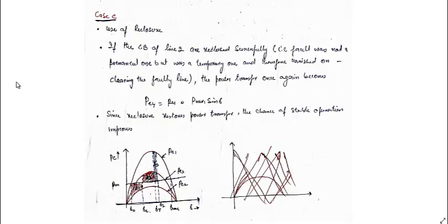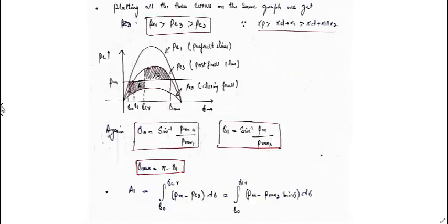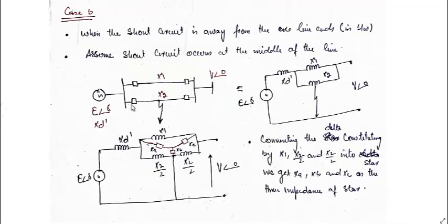You can see that when the reclosure happens, these two circuit breakers have been closed again. Which ones? These two circuit breakers. The fault is cleared first, so the line is removed when the fault occurs. This is the same thing done in case C also until now. But before doing any inspection and then restoring this line after one day, half a day, or any number of hours, these two circuit breakers are reclosed again to see whether this fault is permanent or not.